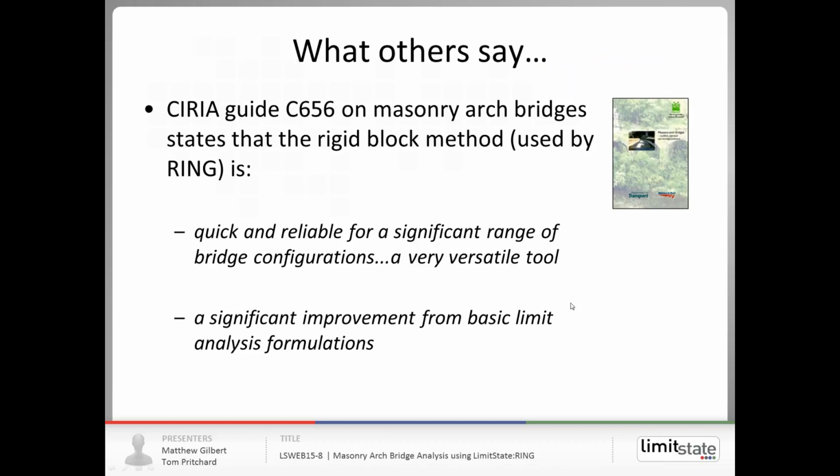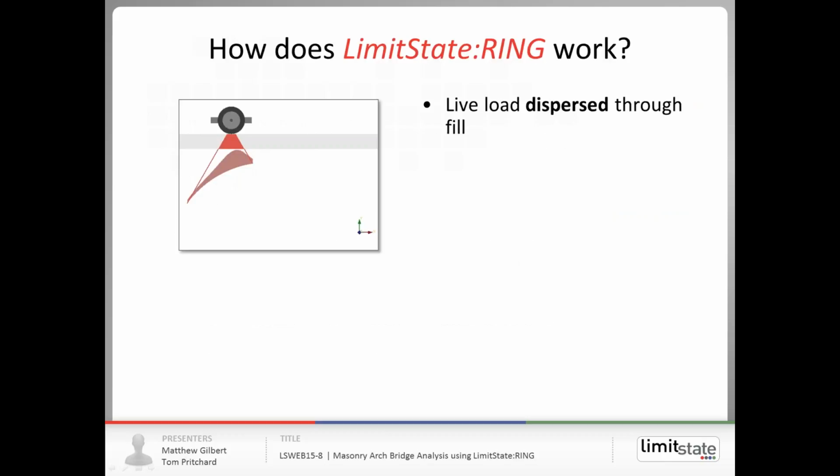The software is mentioned in various industry publications. So, for example, the UK publication CIRIA Guide C656 talks about the method that's used by the software as being a very versatile tool and a significant improvement on the more basic limit analysis formulations that were pioneered in the 1980s and before. In terms of how it actually works, what we do is we assume live load is dispersed through the fill onto masonry blocks.